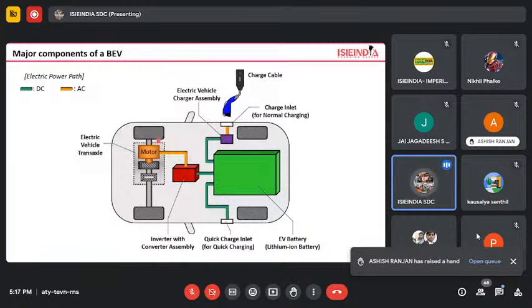While you are cornering, or in off-road use, or even on an irregular surface, we need to differentiate the speed from the left side, maybe a different speed on the right side, depending upon the road condition. So normally the differential's purpose is to make the difference during cornering. But if any tire is going abnormally faster than the left or right side, that time the differential will differentiate that speed variation.